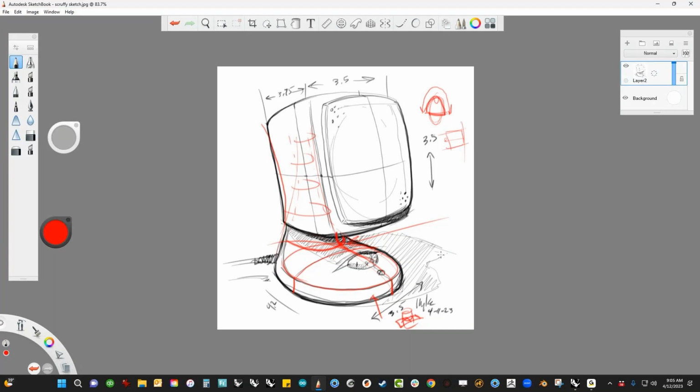We're just going to overbuild all that stuff and trim it back. And if you're new to Rhino or new to 3D modeling, you don't know what overbuilding is. Overbuilding is if I needed a surface, I'm going to build it bigger than I need it, and I'm going to just focus on the part that I'm going to trim out. I'm going to trim out all this stuff, or maybe the top, and that will get me this kind of shape that's got my little crown part on it. So that's what we refer to when we say overbuilding. We're going to build the surfaces bigger than we need to and then trim them back.